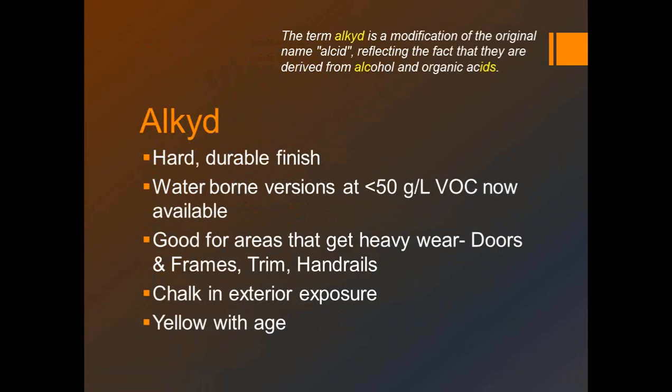There have been some good headway made in not having that situation be the case so much. But I would get with your paint manufacturer and take a look at the DTMs, especially going into the fall season, to make sure that what you're using does have maybe, if not a cold cure capability, at least the ability to cure out in cooler temperatures.